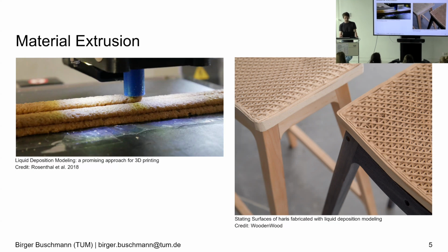The drawback here is that the liquefier, which is necessary to bring the material out of the nozzle, needs to evaporate to solidify the part. And this evaporation leads to voids in the material and in turn reduced mechanical properties. Because of that, there's currently not a real application for this process.